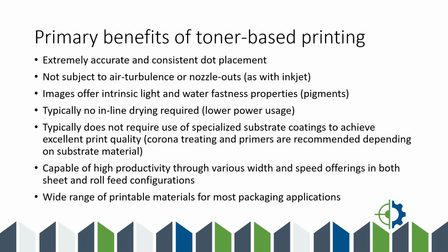However, there are treatments that are required. Corona treating, that's part and parcel with toner. A lot of substrates you can purchase from media suppliers will be Corona treated for toner presses. However, you typically will have to refresh the Corona charge on a machine. There are options on presses that will do the Corona treating as it's feeding into the press.